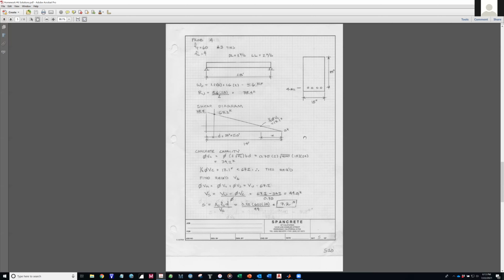Right. Yes. Now I can say in common practice in the real world, we don't do this. It's just not worth it. So we'll step down: you need a lot of ties at the end, and then you could use half as many ties in the middle region, but we won't go to a point of no ties. We don't do that. It's just not worth it. So we'll put a lesser region in the middle and a more tightly spaced region at the end. Okay, that makes sense.